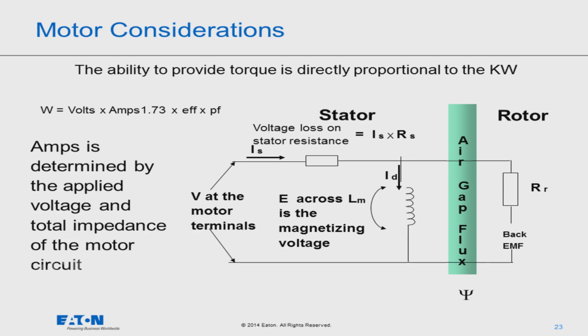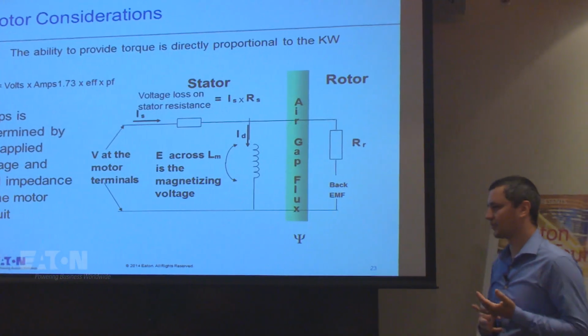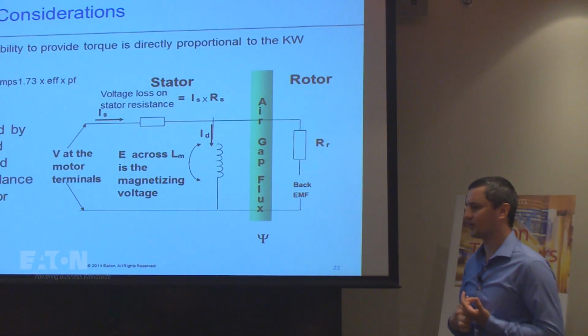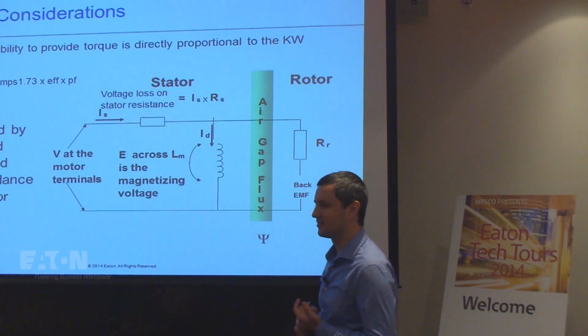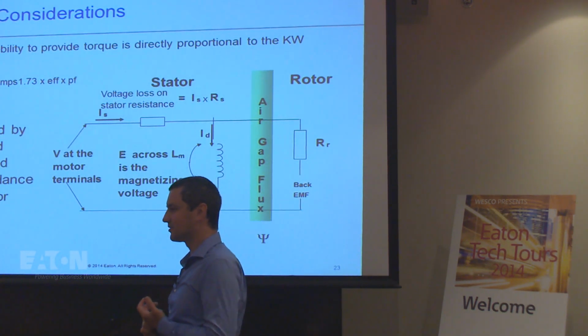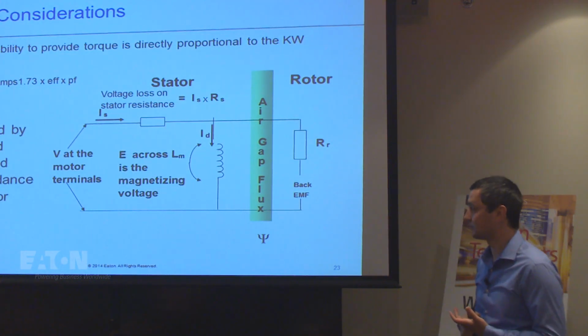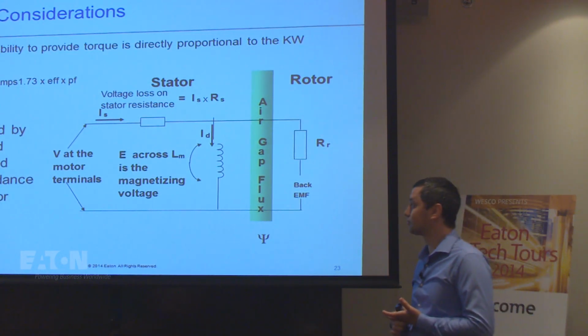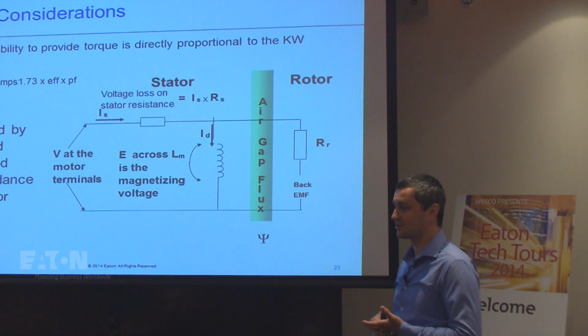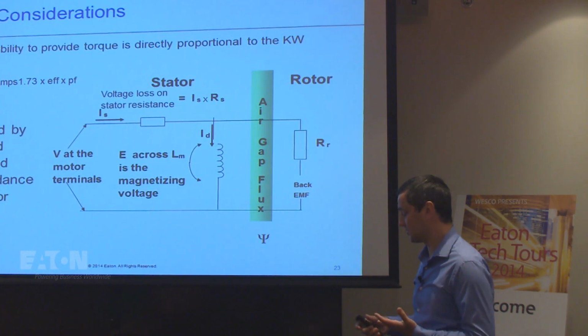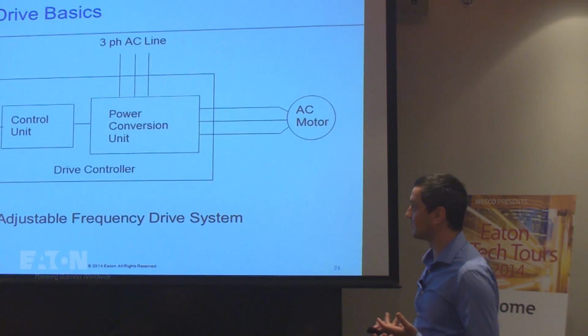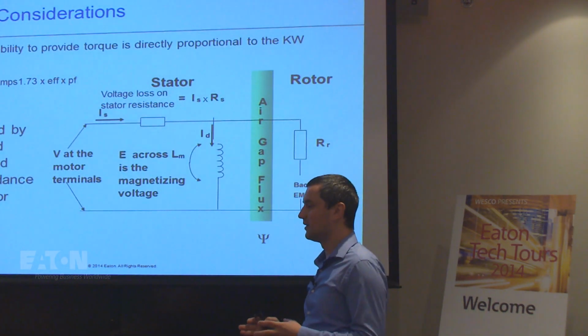What do you think is forming the impedance in a motor? Do we have capacitance in there? Okay. What kind of capacitance? Between different elements of the windings, basically, because you have an air gap, okay? So you have some capacitance. Resistance, of course, in your windings and stuff like that. So these are the elements, basically, that will contribute to that.